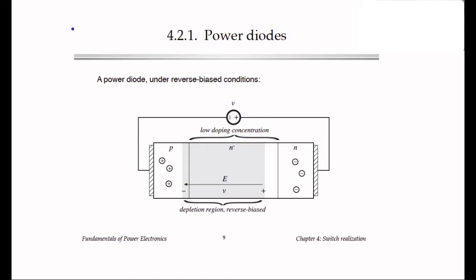In any semiconductor device, the breakdown voltage is related to the doping concentration of the silicon material. Basically, silicon with heavy doping has a low resistance, but it also breaks down at a lower electric field strength than if there was a light doping. This is a fundamental characteristic of avalanche breakdown in semiconductor devices. And so in a diode we have to include a low doping concentration, high resistivity region in order to achieve a specified breakdown voltage.